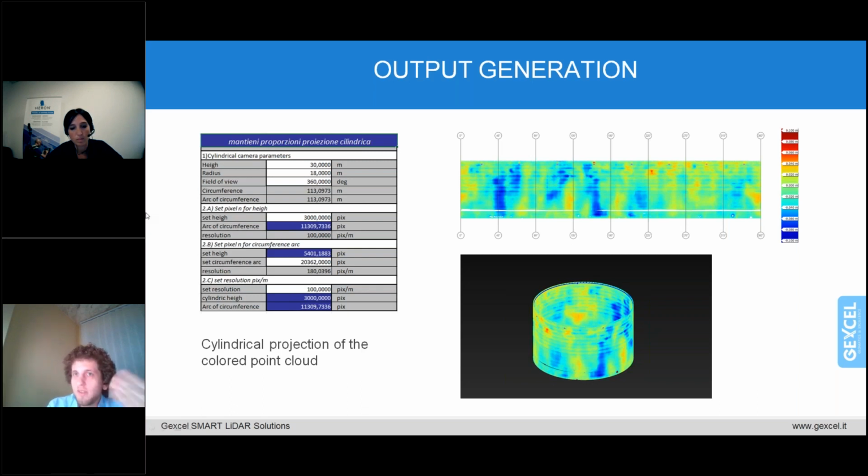which already is an interesting thing because these days, as the usage of point clouds gets more and more common, you can just send it over within a Recap or any free viewer format, and that's also a result. But if you want to provide a classical way of deliverable, a 2D format, a PDF, you can find a way within Reconstructor to unwrap this cylindrical surface.